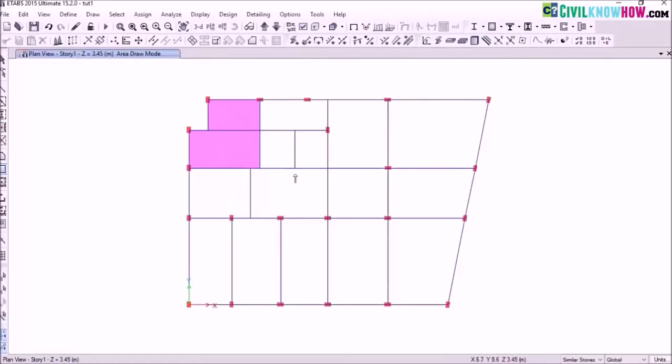but there is an alternate method which is much more effective actually, and you can save a lot of time too. That is, I'm going to select the slab from here to here. So over these 3 sections actually I have assigned a single slab. By adopting this method I can save a lot of time. That is, I'm going to select the slab and the frames. So I need to split my slabs between these 2 frames.